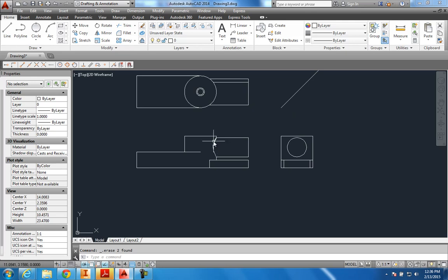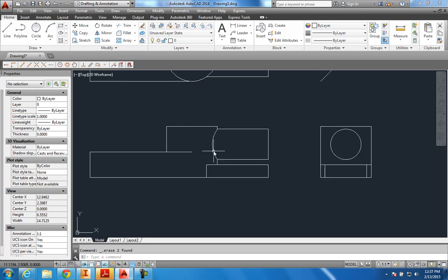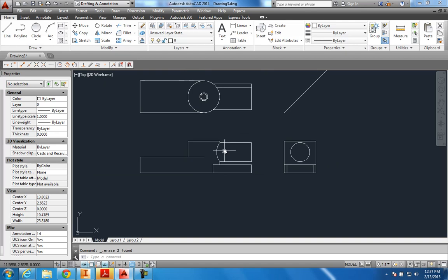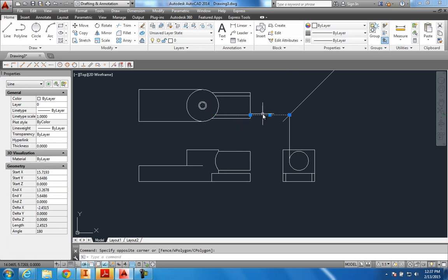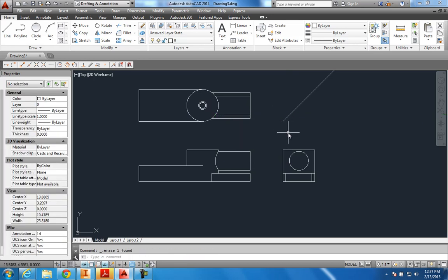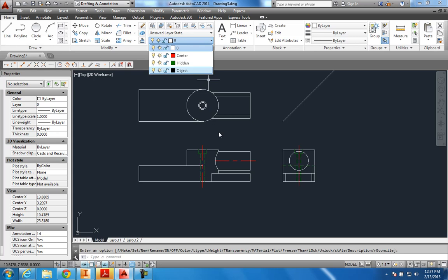Now when you have two cylinders that come together that are the same diameter, usually they'll make like a V pattern, but if they're not the exact same size, you've got to go in and plot these curves, and I would even recommend plotting the curves to even do the same diameters. It'll be a V type shape, but go in there and do that and it will help you out tremendously. But again, make sure that you read up on that in the book, the assigned readings that I provided for you, and it'll make a little bit more sense when you get into and start drawing these. So this is what the top, front, and right side orthographically would look like on this object.